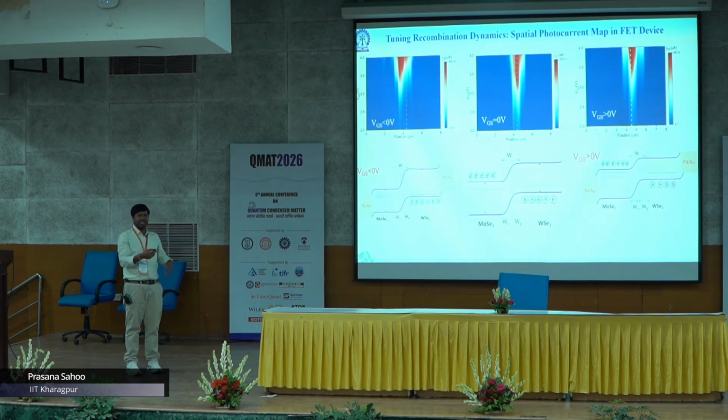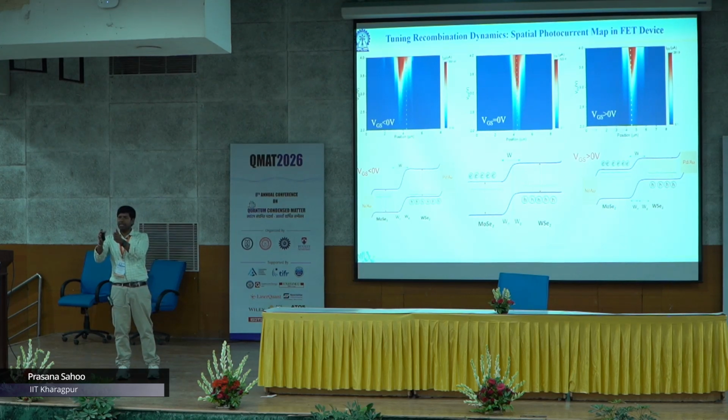What is more fantastic here is that, unlike in a conventional semiconductor where we cannot access the interface, here we can see the interface, and we can control doping individually. That gives us flexibility. By allowing electrostatic doping, we can modulate the interface junctions. So we can indeed shift the depletion region depending on the type of doping.